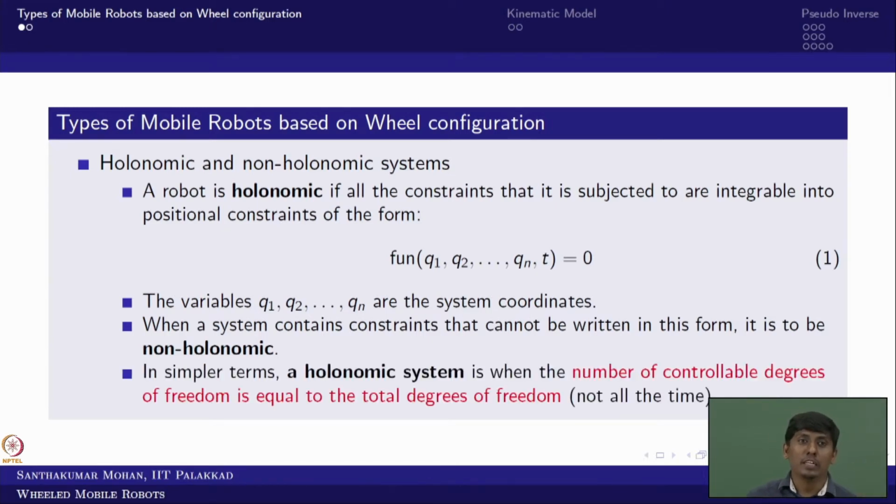For example, you would have seen skid steering, right? Why it is called skid steering, I did not tell there. If you have a simple differential wheel with only 2 wheels, it would rotate as well as maneuver. But now you have 4 wheels and you control each of the 4 independently. What happens is that it would go very fast, and as well it is sliding in real time. That is why it is called skid steering. It is not a steering system, but the rotation can happen by skidding. That is the idea.